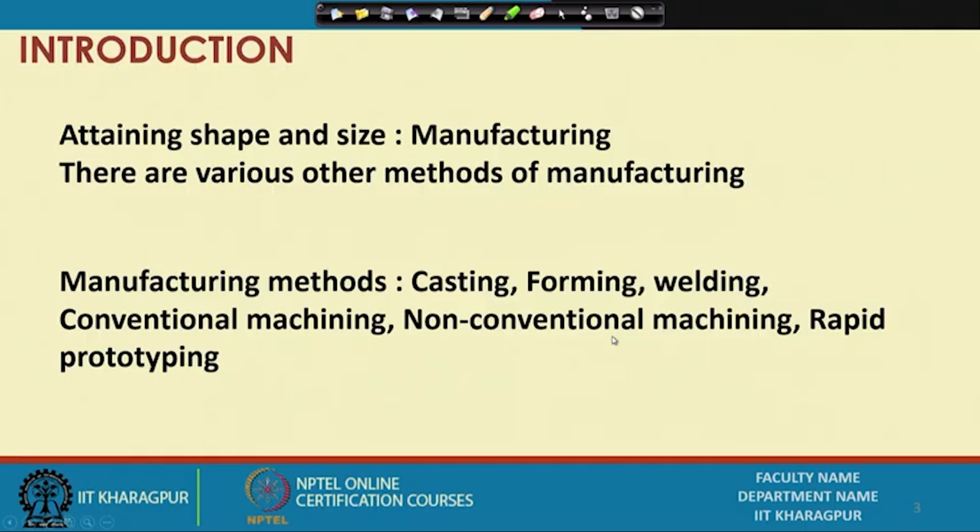There we are not applying mechanical forces in order to remove material. Non-conventional machining can also use electrical discharges across a gap, so that these discharges cause thermal damage to the material. That means it simply heats it up to such an extent. That is called electrical discharge machining.